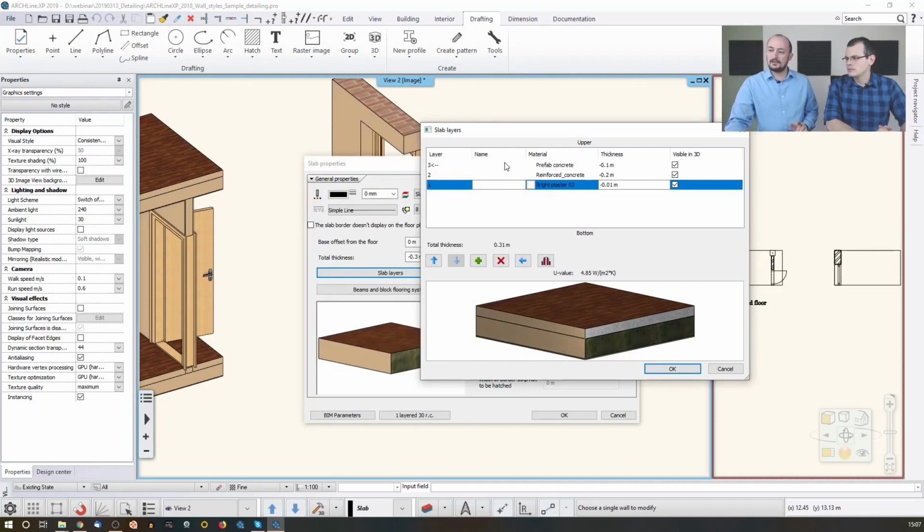There is also a name field here, and this is good because these are more descriptive than the material name. Now the material name is bright plaster or something like that, but I can type a real maker name or something like that, because this is what I will see at the end in the quantity takeoffs and the schedules and things like that. So I can add those details, but on the other hand, there is one last thing at the end of this row.